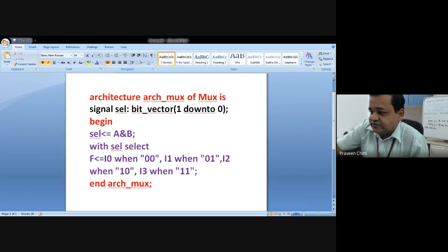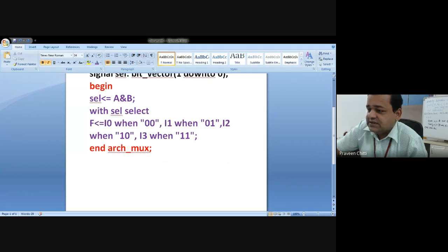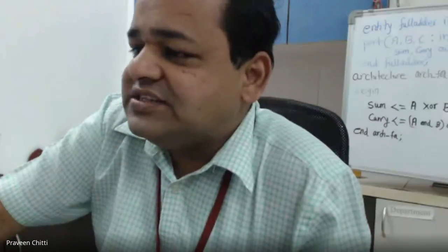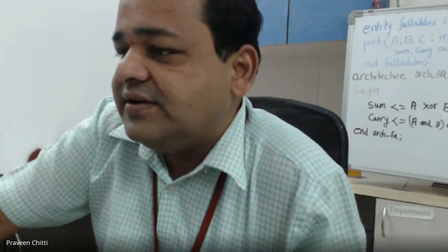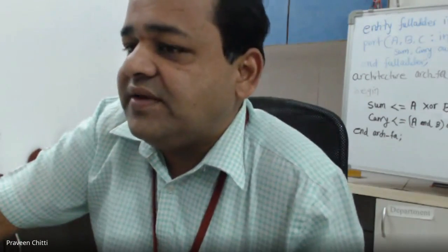So now we'll see how we can use that full adder program to write the program for the parallel adder. I hope all of you know the parallel adder. What do you mean by parallel adder? So parallel adder is what? Full adder adds 2 single bit numbers along with the carry, whereas parallel adder can add 2 multi-bit numbers. For example, if you call an n-bit parallel adder, then it can add 2 n-bit numbers, and it will give you sum as n-bit, and there may be an end around carry also.